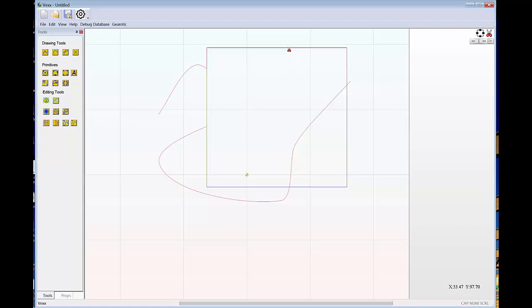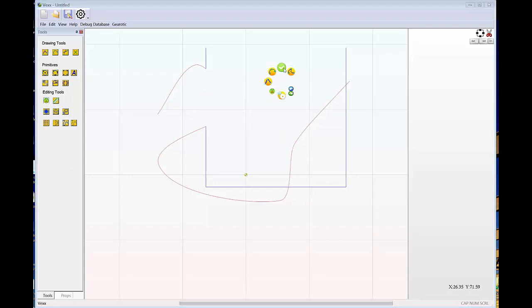Now the control key is also used as a modifier. Here, for example, if I hover my mouse on this box, you can see that we're selecting from the beginning of this Bezier curve to the beginning of the intersection of this Bezier curve. And if I click, we'll remove that entire area. Now if I back up, the control key tells it to select single entity only, which means that if I hover over, because this square is built of 4 entities, 4 lines, by hitting control I can say I only want to snip 1 entity. So between the 2 shift keys and the control key, you'll find that clipping your diagram is actually fairly easy.